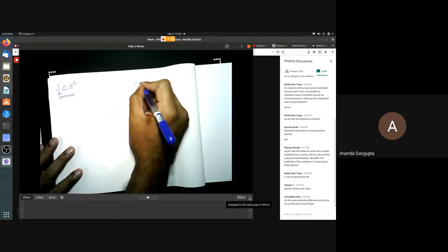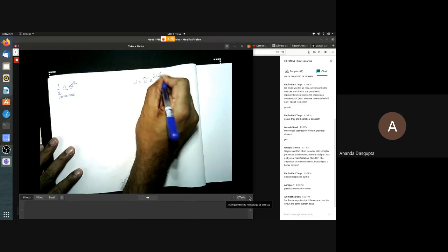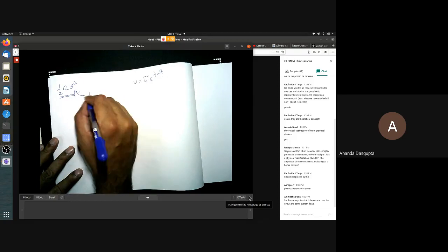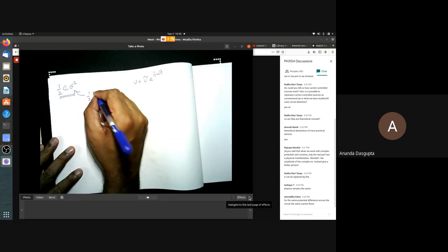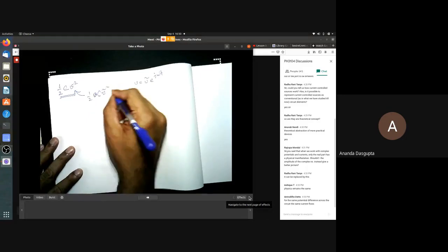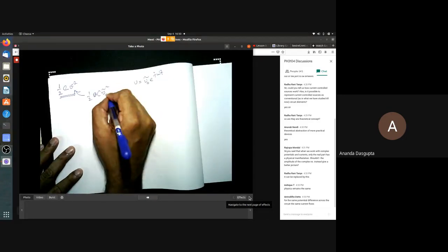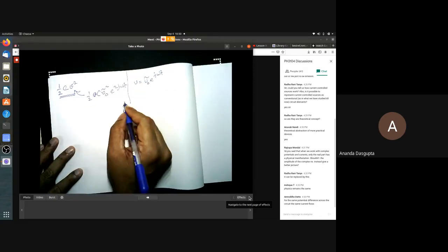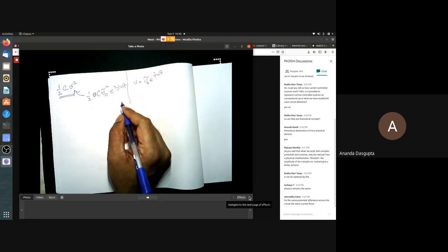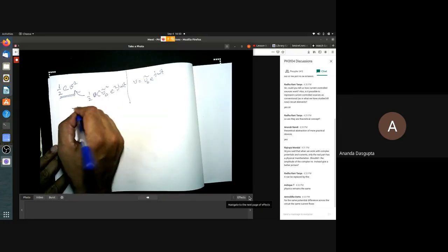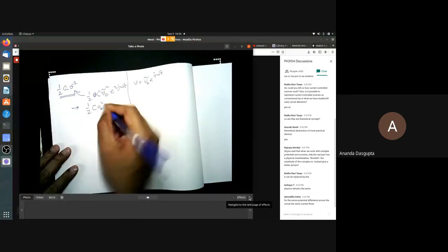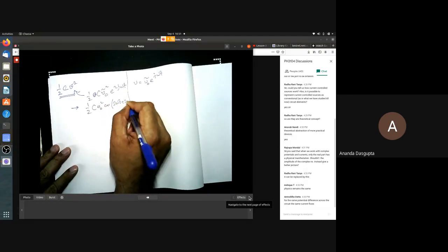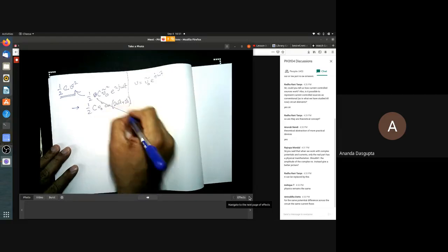Now, if V is V tilde e to the j omega t, if you plug that directly here, you get half C V tilde squared, or V tilde 0 squared, e to the 2j omega t, and then try taking the real part, because after all the energy has to be real, you end up with half C V0 squared cosine of (twice omega t plus twice delta) or something. This is completely wrong.